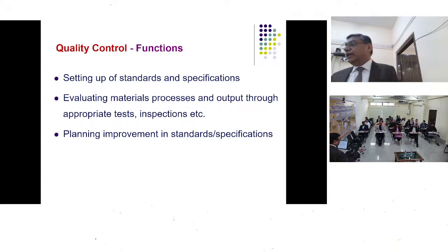Then when that material is being put on the construction site, whether it has been evenly spread or not, whether the rollers are proper, and whether the proper thickness of the layer, as dictated by the design drawing, is put. For example, we say that I'll have a layer of clay of 30 centimeter uncompacted, and the compacted layer will be maybe 22 or 23 centimeter, depending upon the density.